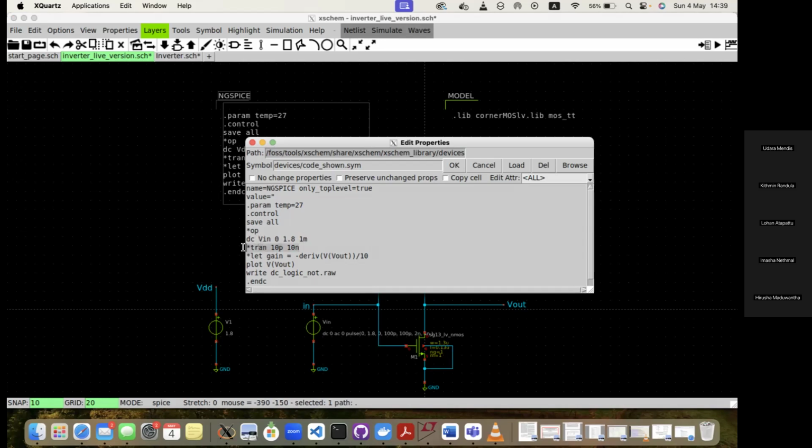And this is a transient simulation. This works similarly to commenting, so I am not using this command when I use the star. So this is a transient simulation. In the transient simulation, I'm simulating up to 10 nanoseconds using a 10 picosecond time step. So yeah, time units.